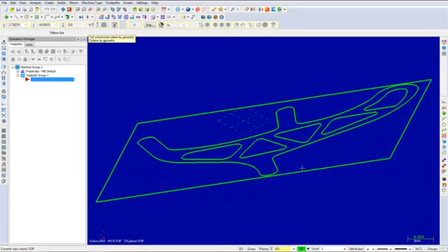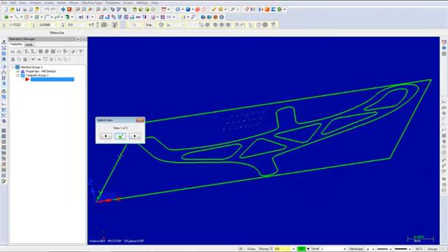Select the following two intersecting lines as shown. Your axis orientation will appear as shown. If your axis does not appear as shown, from the Select view, choose the Next button until the axes are matching. You can now select the OK button to continue.